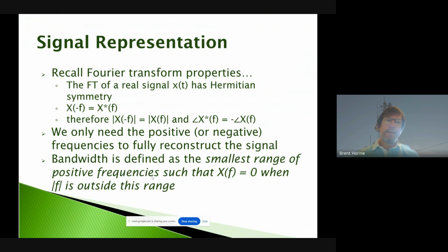And that now gives us a lot of resolution in the frequency domain. So we can look at different slices of frequency and look at what the amplitude of that signal is at that frequency. Basically, each amplitude at each frequency is contributing to the overall signal. Note that we've lost all our time resolution when we've done that.